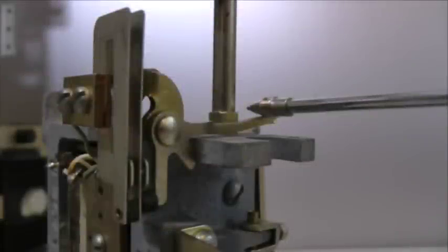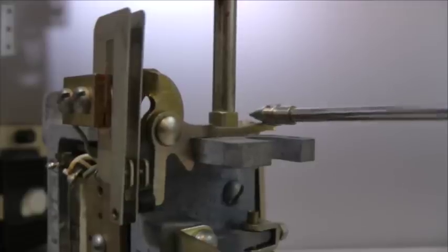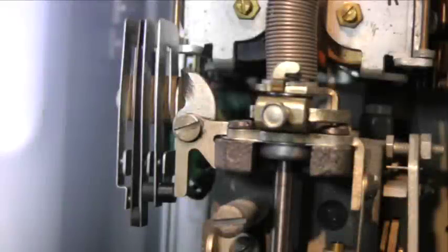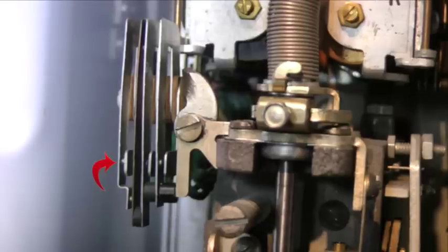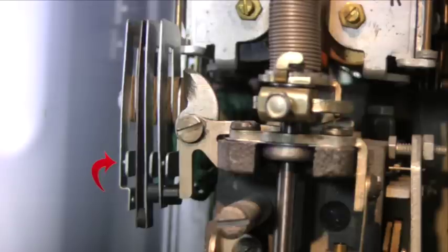For clarity, I have added a clip here using my spare part switch, showing the mechanical motions of the off-normal finger. The off-normal finger pivots upwards, allowing the tensioned vertical off-normal, or VON springs, to operate. These remain operated for the duration of the call and play a part in the energizing of the vertical and rotary magnets and the energizing and de-energizing of the release magnet. The wipers move vertically upwards by one step, which brings them in line with level 1 of the bank terminals.